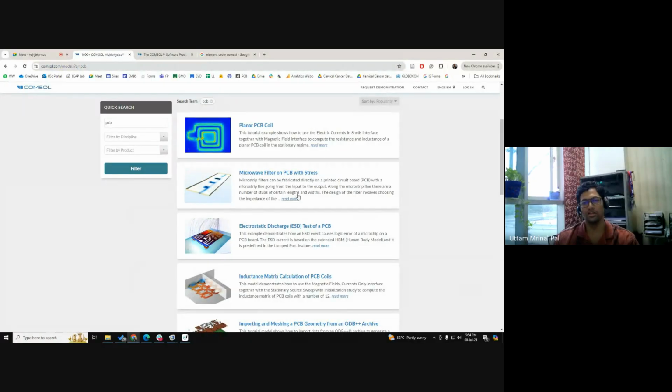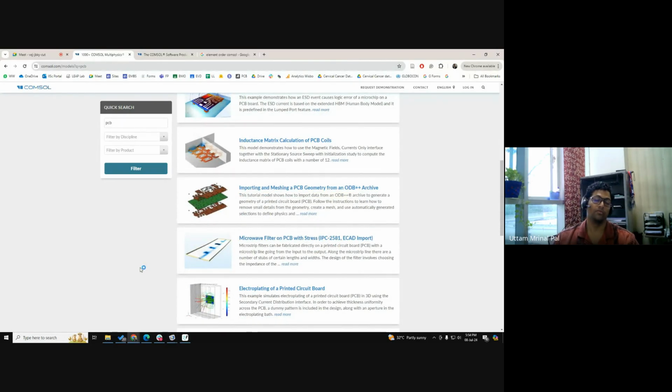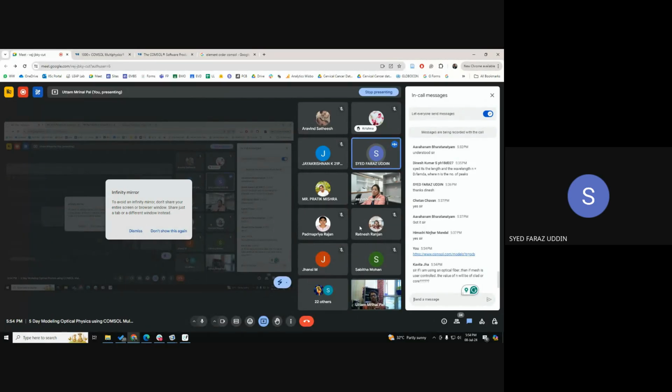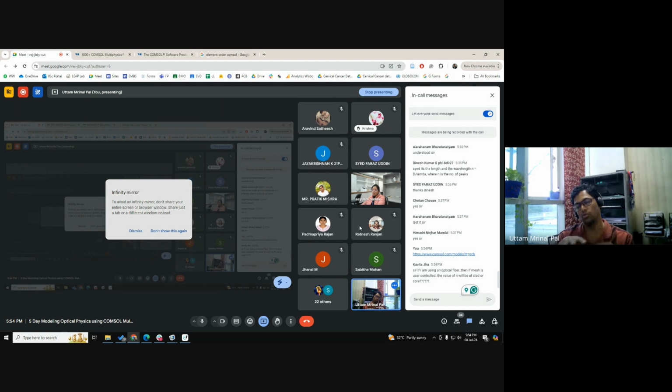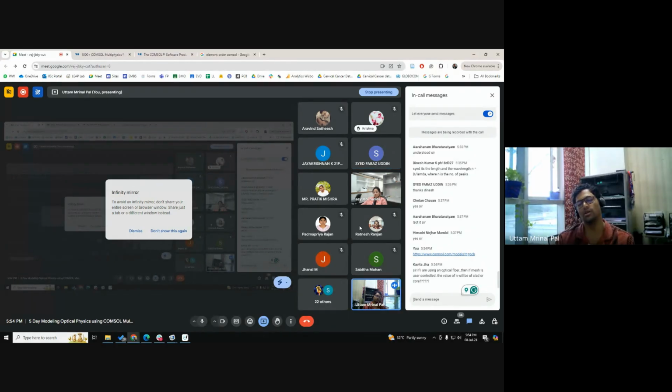So either you model a PCB, or you model the optical waveguides that you're talking about. Eventually, it's just the electromagnetic field. With a PCB, when you're using the lumped port boundary condition, which is not available with the Wave Optics module, you actually need to apply a potential like a voltage. Instead of applying modes, like TE mode or TM mode, x-polarized, in a lumped port we have to give, between two conducting boundaries, the top and the bottom strip, a particular voltage.